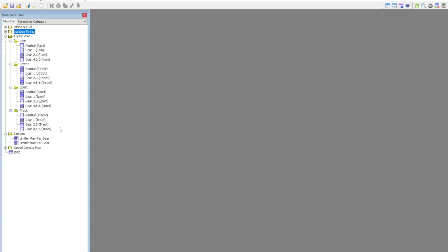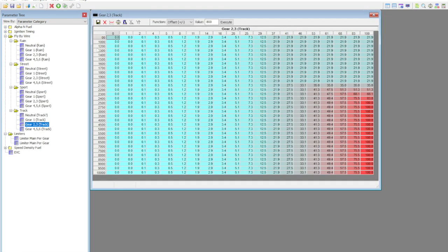Next, let's get rid of ignition timing. Fly-by-wire. Again, you don't really need to make many changes here, unless you feel that opening up the throttle a little bit earlier down here, allowing for more throttle at low RPM, increases power. I've tested that. It doesn't. The KTM kind of nailed this pretty well. You don't need to increase the maximum throttle at low RPM. If you do, it doesn't really make any more power. Actually, it can lose power.